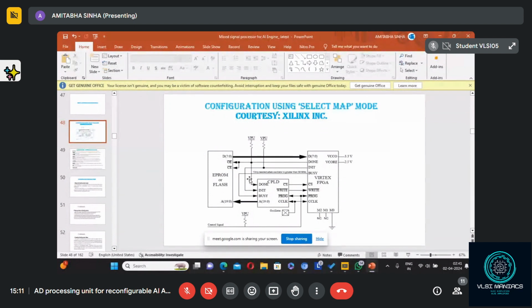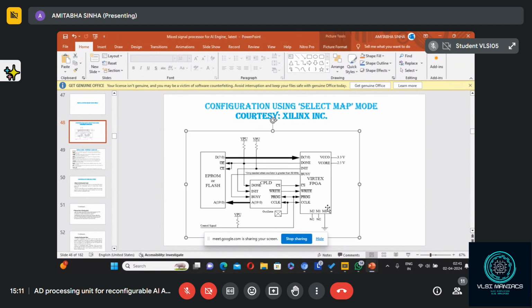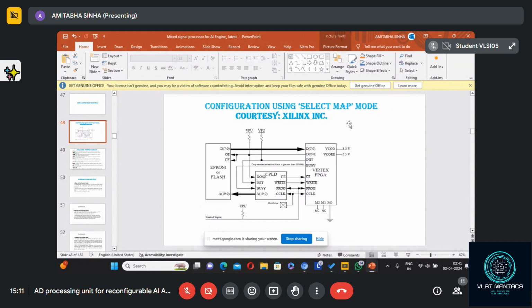Initiations: when it gives the init signal, that means any operations, downloading or anything, can be initiated. So these are the major pins. And there are also some, look, you don't have to mug these things. These are M0, M1, M2. These are basically device specific for some FPGAs. Depending on these M0, M1, M2 signals, it will be in a different kind of configuration mode. That's not very important at this moment.